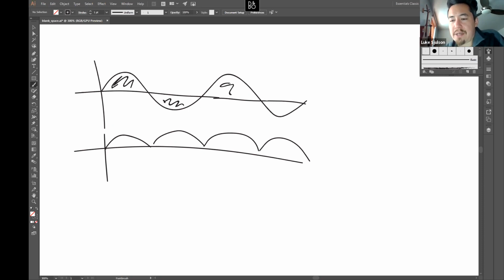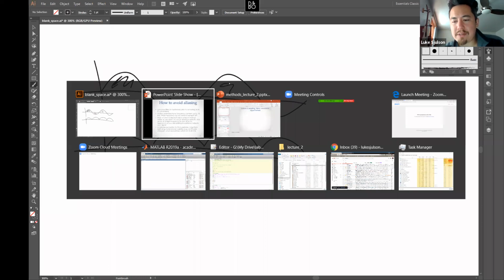Photometry signals, for example, or microscopy can be contaminated with things at those frequencies. The refresh rates of monitors are much less of an issue now that we have flat panel monitors, but even so, you can see noise at certain frequencies, like 60 or 70 hertz. Those are all annoying for things like local field potential recordings, because you're trying to record stuff in that range. You can't just notch filter it.